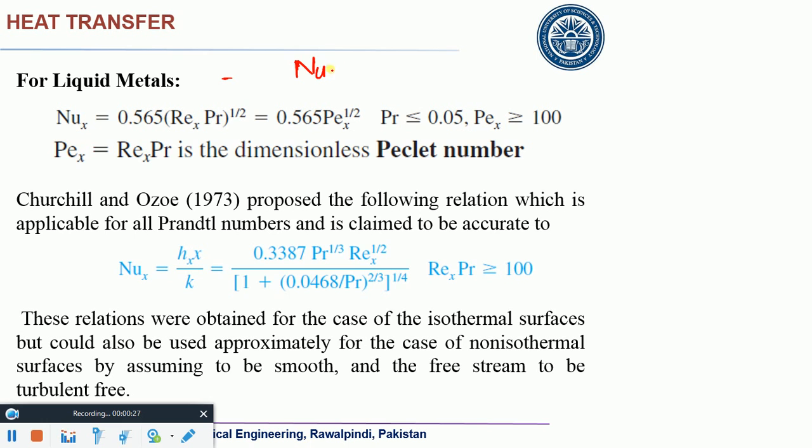remind is that this Nusselt number is a function of this X star, Reynolds number and Prandtl number. And if you put a bar over it, that takes care of the average value, then this would vanish. Similarly, this CF would be a function of X star and what? Reynolds number only. And if you again take a bar, the average value, this X star would vanish. Why? Because you differentiate it with respect to X.